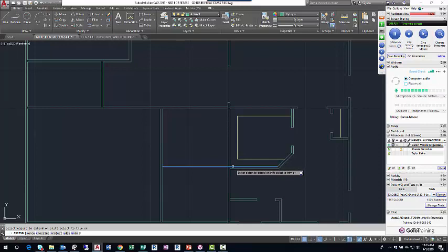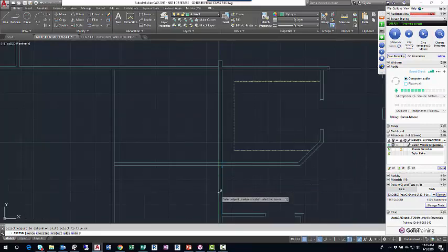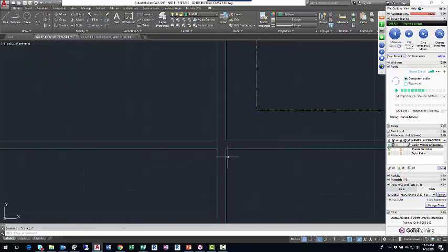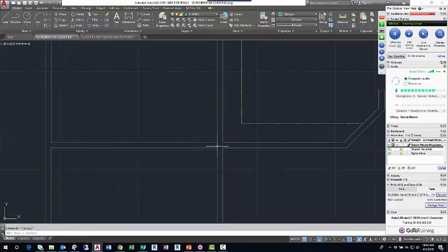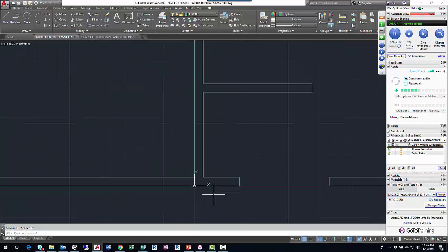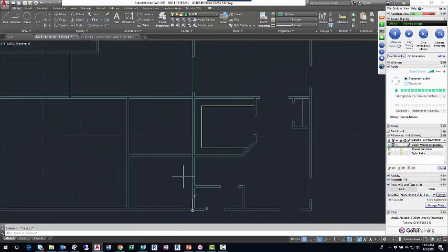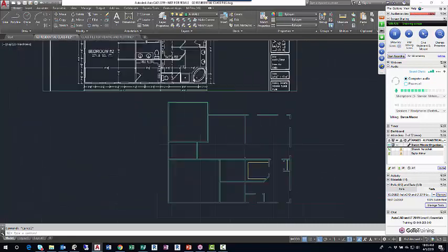All lines are boundaries, like so. And then when I'm done, I'll hit escape, and I'll use the trim command. Trim, enter. But maintaining that valid boundary between the master bedroom wall lines and the rest of the floor plan. I want to keep the solid boundary. I can always come back and fix it later if I need to.